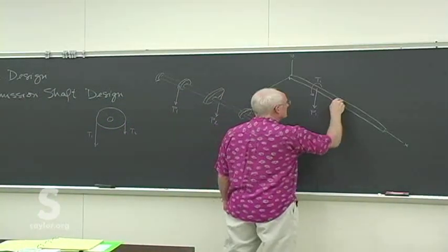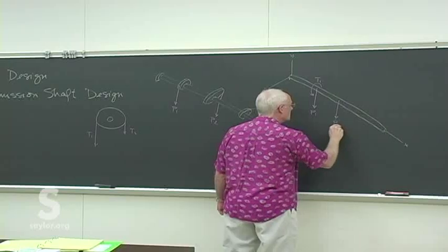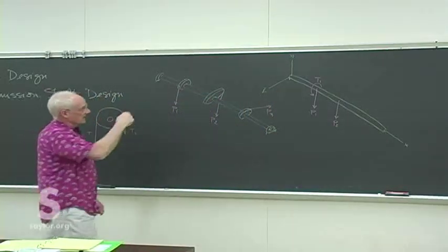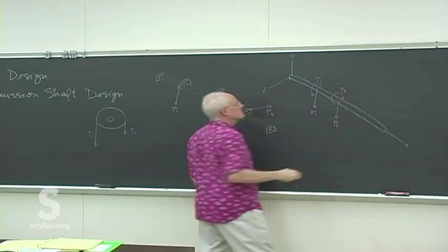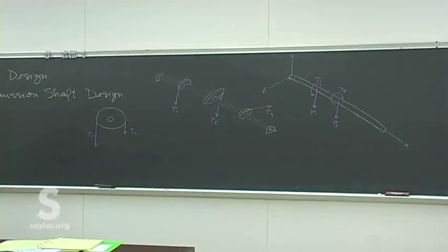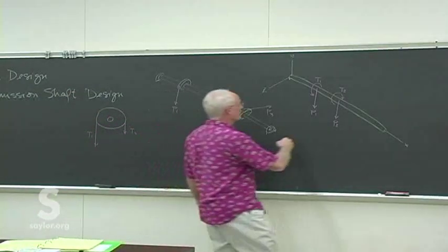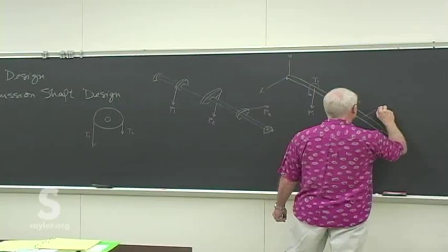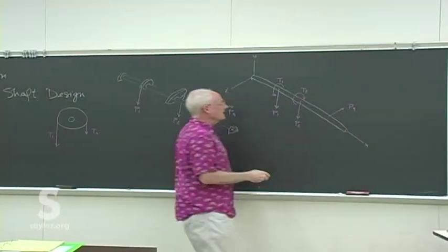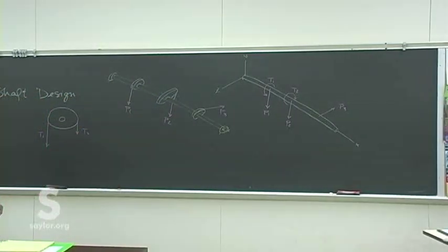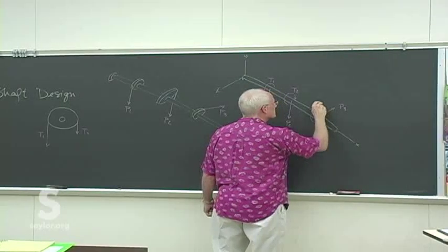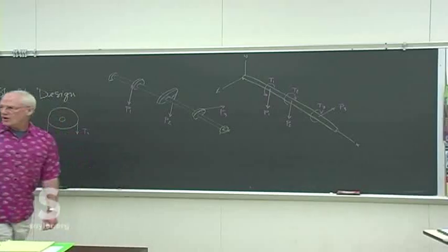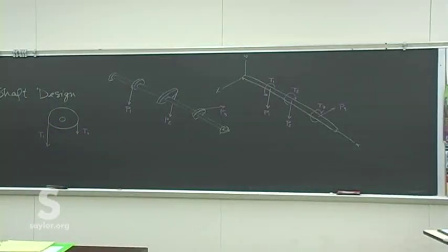And there's a P2 there as well. And it's causing a torque in the other direction because it's on the other side of the gear, which is trying to twist the shaft in the other direction. And then even another one, P3. This one happens to have a component in the Z direction and will also cause some kind of torque. So take a little time just to draw those in so they're in their general senses. They kind of make some sense with what we're doing.